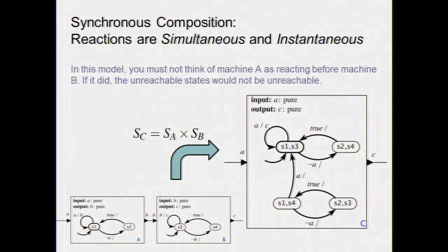Since we exhausted all the possible combinations of input, present and absent, is this a finite state machine? Yes and no, because we have these other states that we have to take care of. Because we have walked through the machine, it's obvious that the other states are going to be unreachable, otherwise we would have seen them.